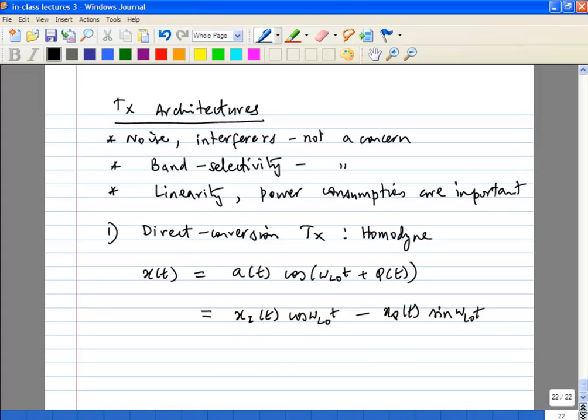Now remember that this signal is actually a real signal, it doesn't have complex components. However, people do talk of what is called a complex signal because remember these are the two things which you produce from the baseband. So you produce an in-phase component and a quadrature component, if you think of it in terms of Cartesian coordinates. So what you produce from the baseband are in-phase and quadrature, or amplitude and phase, depending on if you have